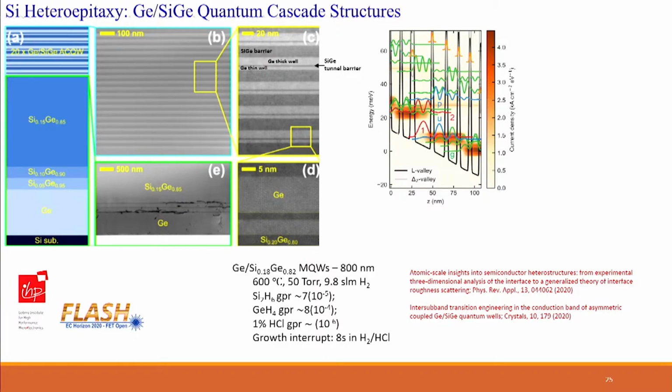You start with silicon, grow the germanium layer like the one I showed you. Then you slowly grade the composition down to about 85% germanium. This forms your buffer, and then you grow the multi-quantum wells. So these are the growth parameters. Why group IV? Remember, these are inter-subband transitions. You really don't care whether the material is direct band or indirect band. It's not from conduction band to valence band. This is intraband. The lifetime of an electron in non-polar semiconductors like silicon germanium is mainly determined by interface roughness scattering, not through phonons. So in principle, you can make them work at room temperature.